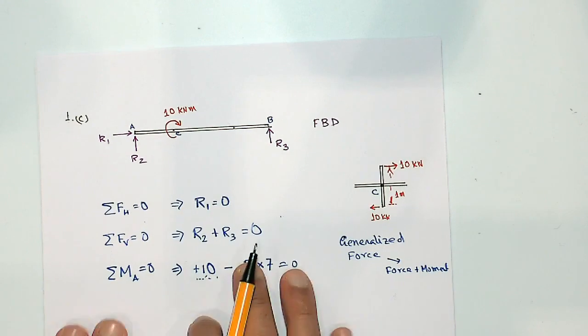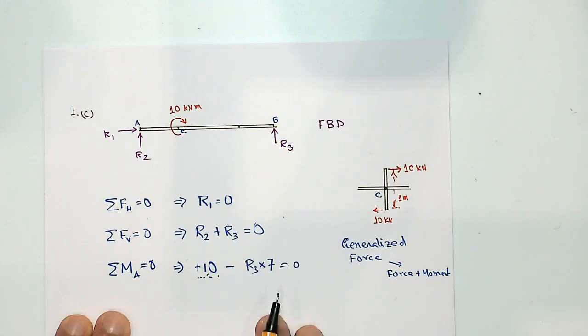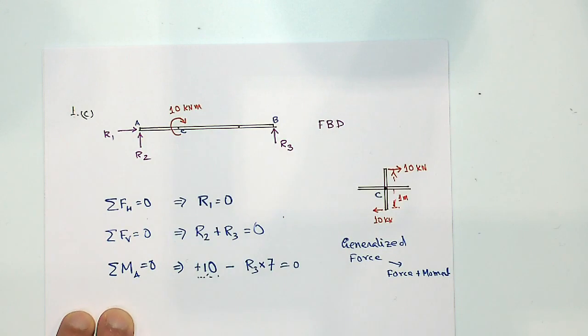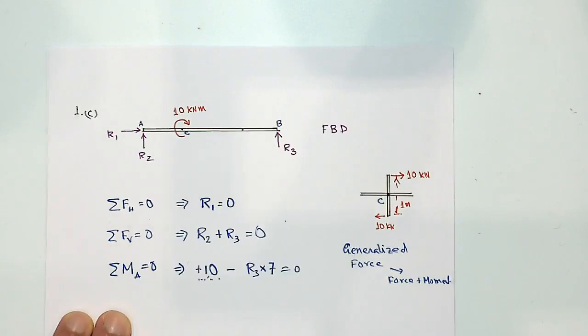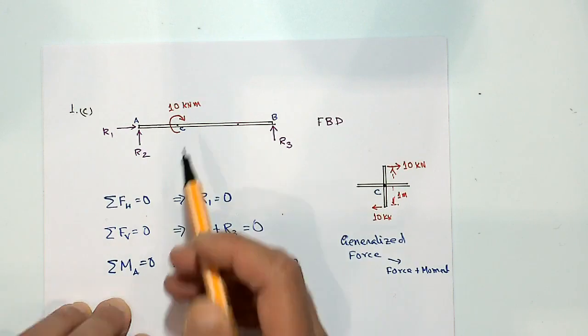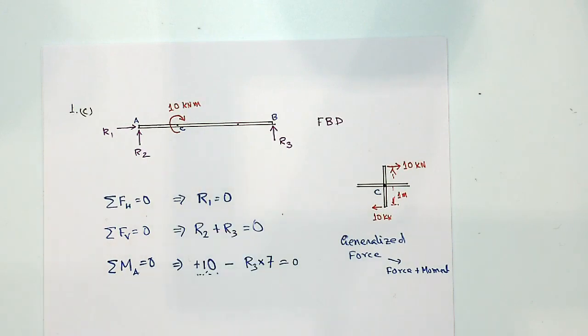Many students in year 1, in the first few weeks, find this part difficult to conceptualize. How come this doesn't change with where it is applied? Of course it will affect the result in the way the beam deflects. So on the deflections it will make a difference, but not in terms of the reaction forces.